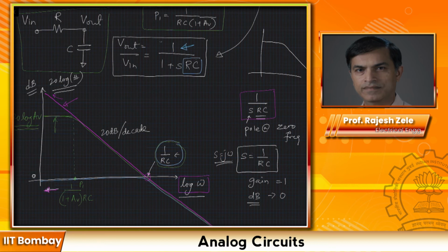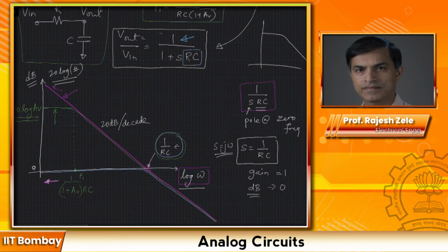And the blue part, what I'm showing you, is actually just an RC filter. The interesting part of the RC filter is the DC gain is 0 dB. Okay. So there is no gain provided. The corner frequency is still 1 over RC.